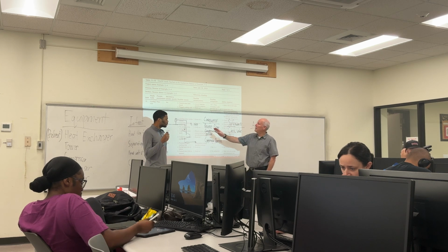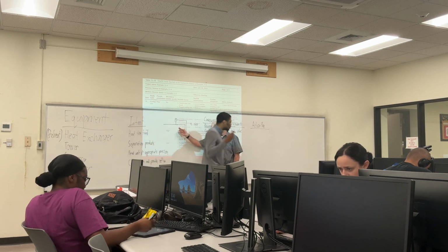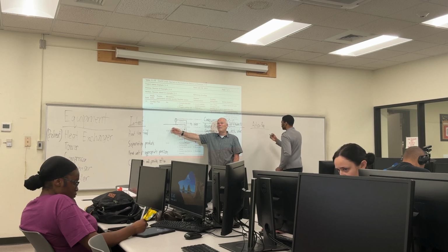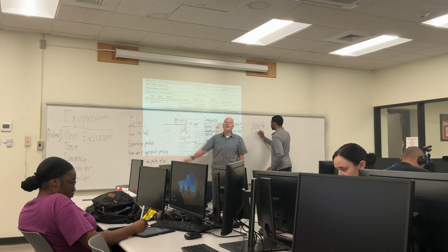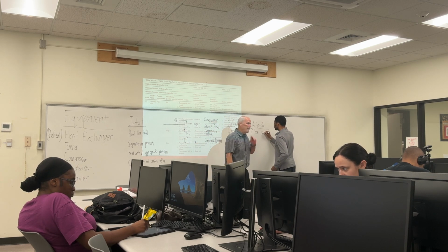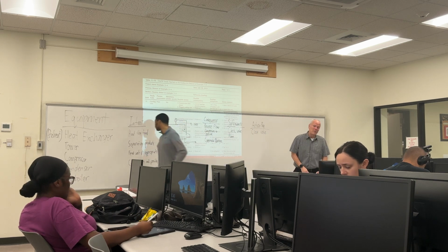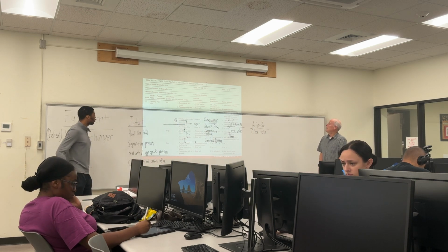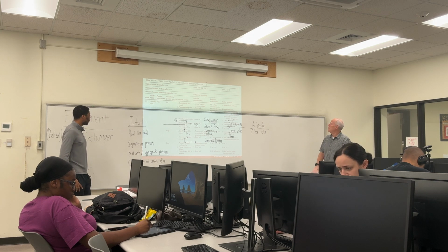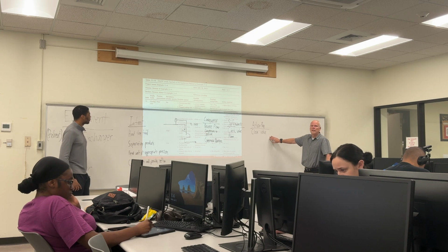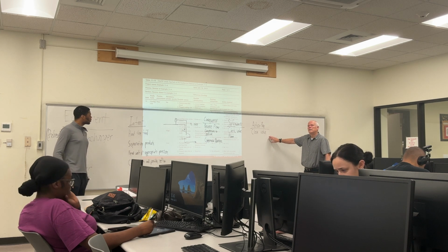You'll have a valve here, right? Maybe you have a check valve there, but you'll also have a valve there. You'll close that valve. Now that may be a big valve and it may take a long time to close, but by God, you're going to close it. Somebody's going to anyway. You'd probably be doing it automatically, but that's the action you have to take.